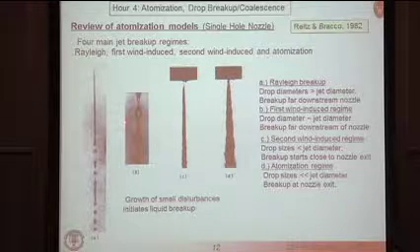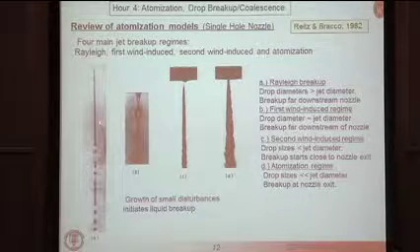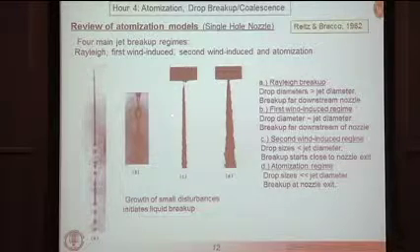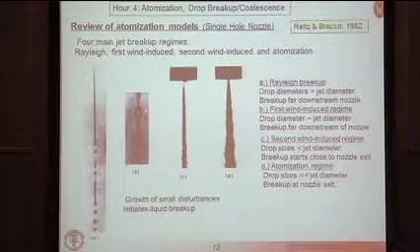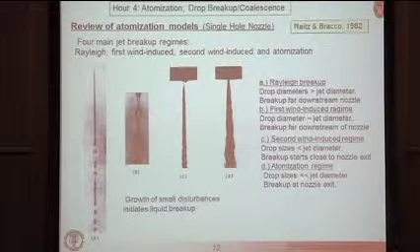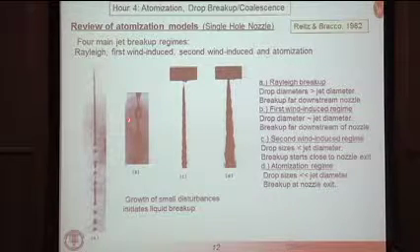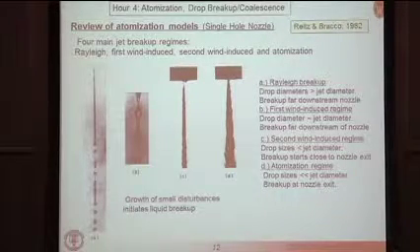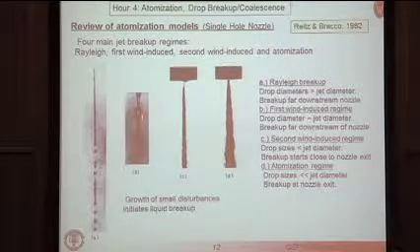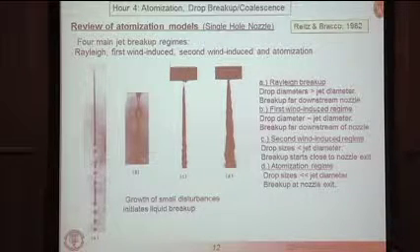So as you increase the density of the environment, what happens is that as these waves grow on the surface of the jet here, they kind of look like airfoil sections. The dynamic pressure in the gas lowers the pressure at the crest of these waves, which augments the breakup process. So you start to see an impact of the gas density in the environment, which accelerates the breakup, hence the name wind-induced breakup regime.